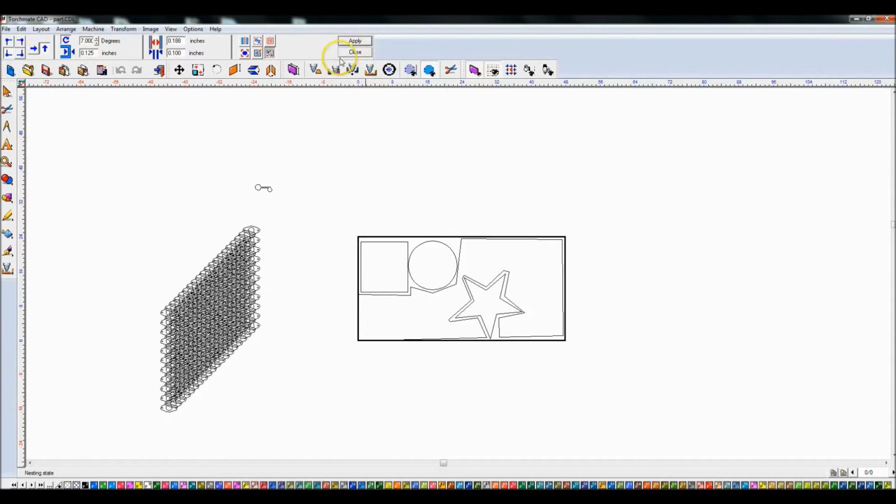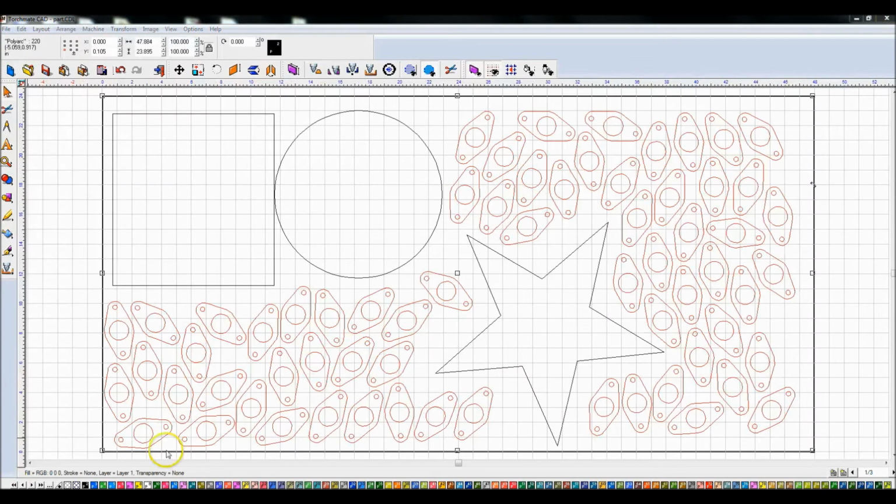And I will pause it so you don't have to sit here and watch it. It's like watching paint dry. So I'll start the recording here in a second. Apply that, it's thinking, we'll pause. Okay, that actually went pretty fast. I was surprised. I did get it complaining about not being able to fit all the parts on the same sheet, but it did go ahead and create them in that area. Isn't that pretty cool? I think that is one of the coolest features about nesting, basically utilizing the material you have and fitting it in there.